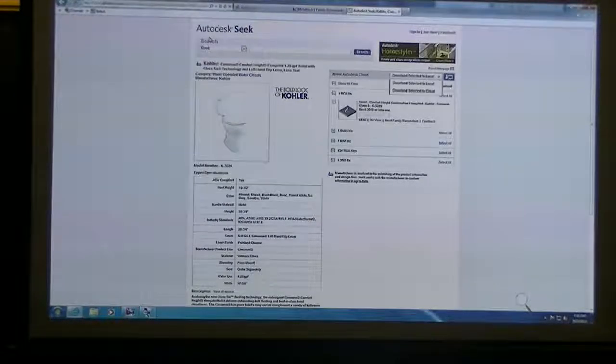Now there are other websites out there like Revit City that's on my website, but I'll caution you. There's the AUGI forum, which is an Autodesk forum where people share. They say, hey, I'm looking for a Butler building steel component. Does anyone have one? And people are sharing files that way. The problem with that, and also Revit City, is sometimes you get a lot of really good models, and a lot of times you get people who've cheated and they've just created a 3D model in Rhino or some other file and they place it into Revit, and then there's no parametric data to it. So if I download a door from somebody, like a garage door, I might only be able to place it exactly how they modeled it, or I'd have to go through the trouble of modeling it again or placing my own parameters.